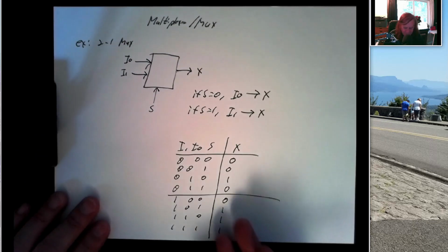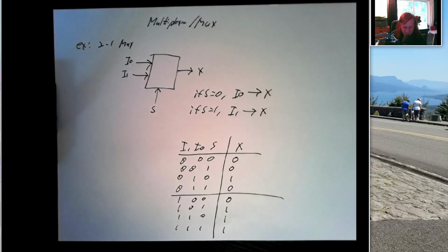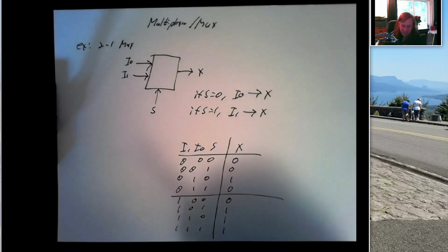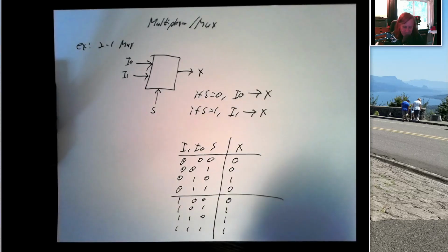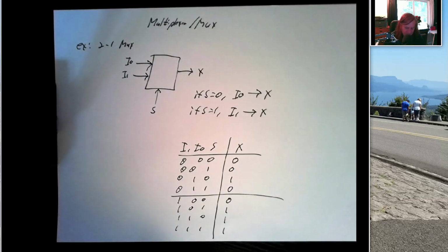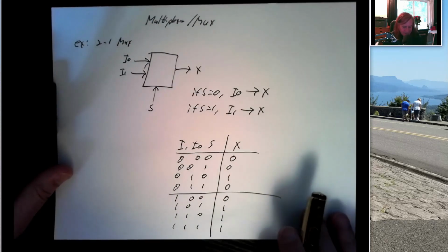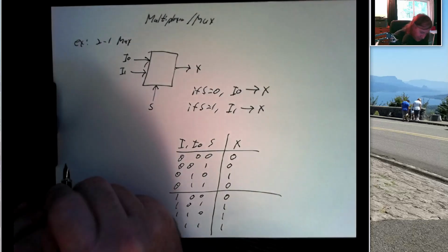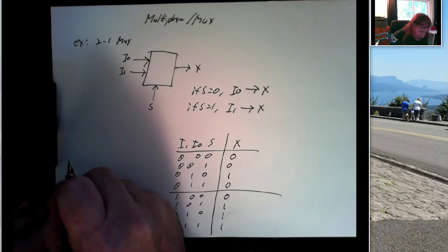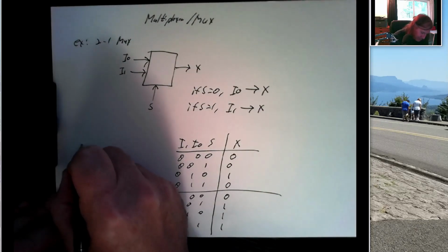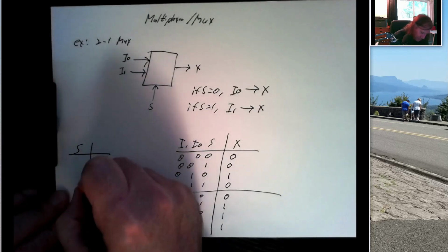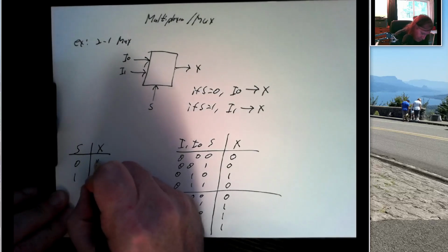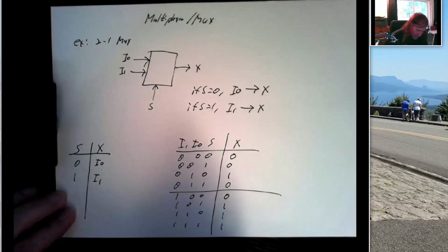And we can write a sum of products, or we can put this into a K-map, and we'll get lots of simplification because we have lots of adjacent ones. We can write an equation and implement it. But there's a different way we can write a truth table that captures this behavior more effectively. And so this is a different type of truth table, right?